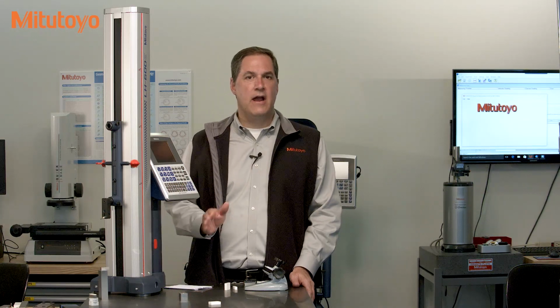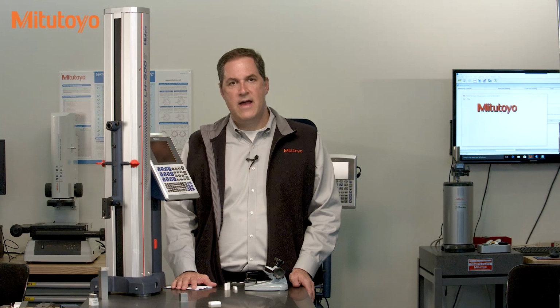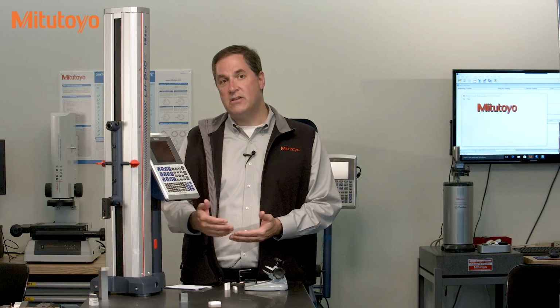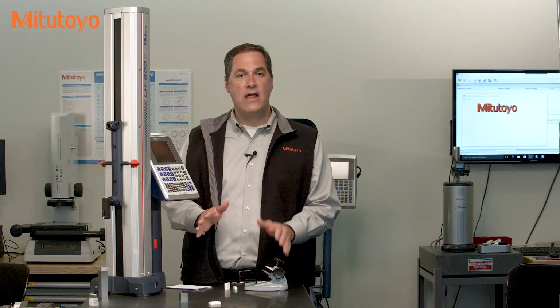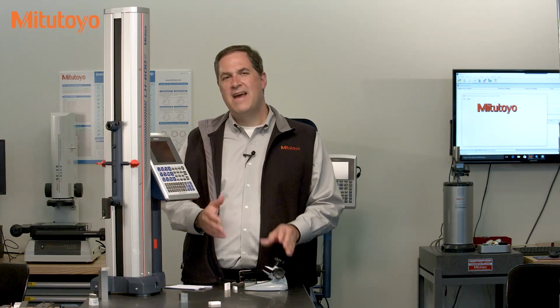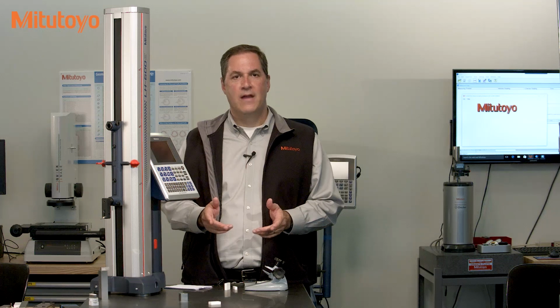So you need to be careful, particularly when hiring calibration services. I've seen some organizations put a requirement in calibration purchase orders that the lab must disclose in advance of any calibration work if the TUR is less than 4. I think that's a pretty good idea and does a nice job of protecting you.